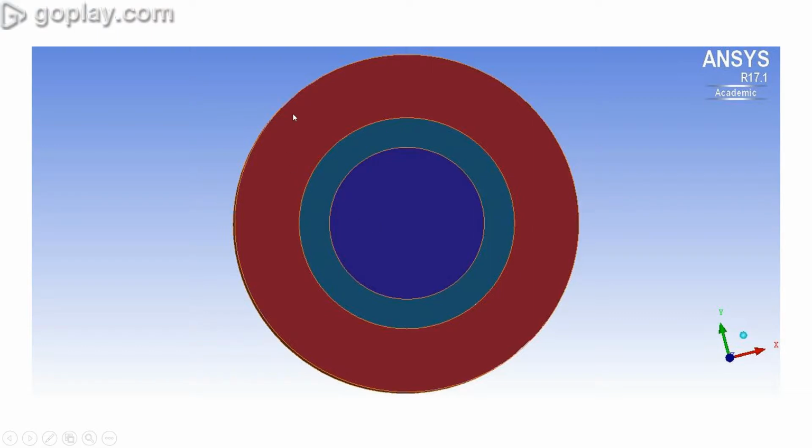Secondly, we have 3 domains here: the outer domain of air, the inner domain of water, and in between, we have a shell, which is a solid domain. So we will also employ the multi-domain mesh. We will create 3 material points and 3 parts with different blocks assigned to them. So let's go ahead and open the ICEM GUI.